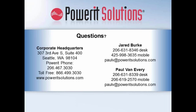Then I could notify the management group at the plant that, let's say at 8:30 I received an email saying that at 9 o'clock we were going to have to be at our interruptible power set point, where we would be going from 4,000 kW down to 2,500 kW. I would set up the program so that at 9 o'clock we went to the 2,500 kW set point.